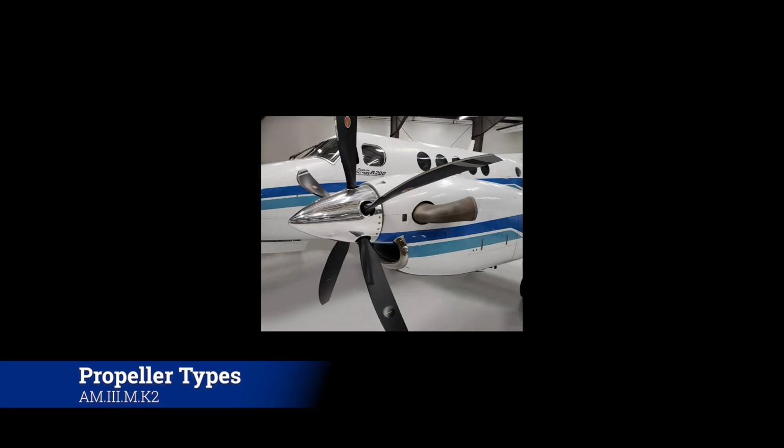And then whenever you landed, you'd have an elongated rollout because you wouldn't be able to feather that prop or put it into beta to slow you down. And so you can see the advantages of those constant speed propellers become pretty drastic, especially on your higher end aircraft that are capable of a lot more. Being able to tailor that prop angle is really essential to operating these more capable airplanes.